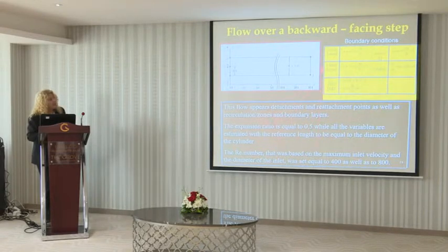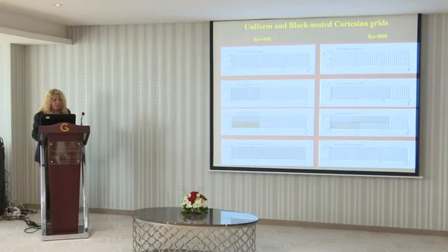In this table, you can see the boundary conditions that we have used. We have given the velocity inlet because normally in industry we have the flow rate given, and we calculate the field in the next steps.